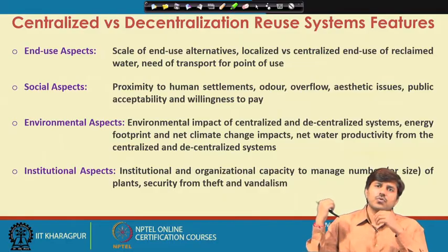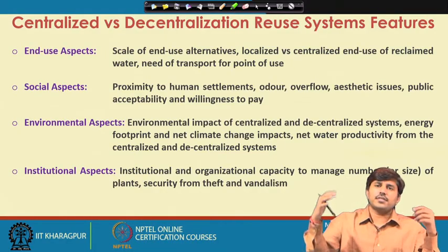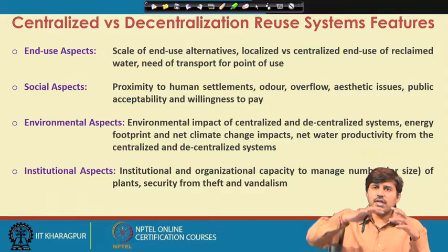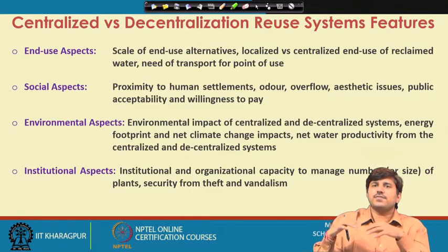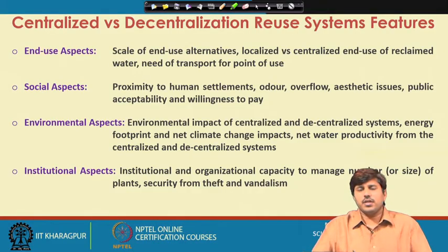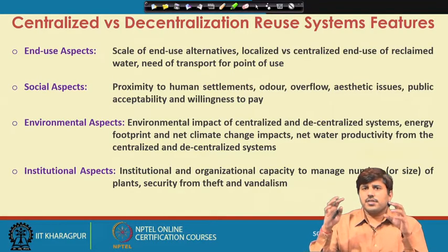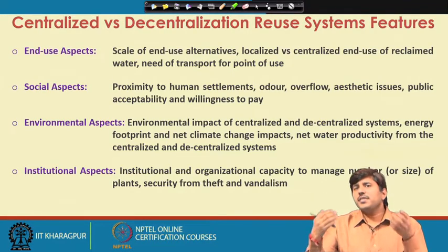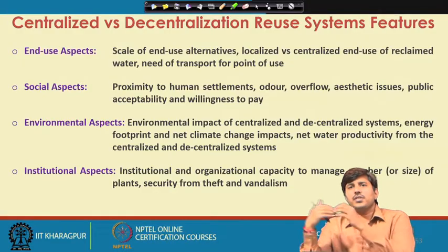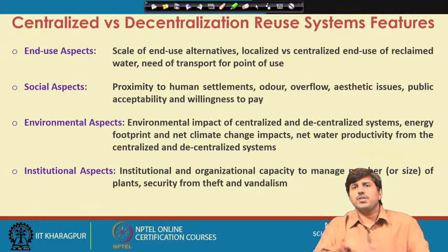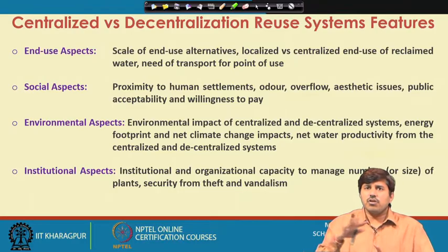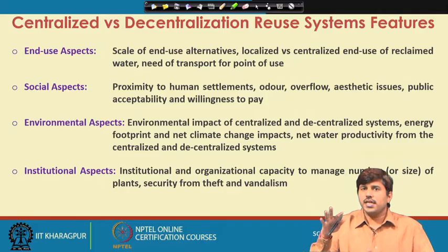From there it goes to different parts of the city along with your water supply network. So, if you go for decentralized wastewater treatment facilities, after treating you have to transport that water to the centralized facility from where you resupply it. So, not much transportation cost is saved if your end use option is again a centralized one.